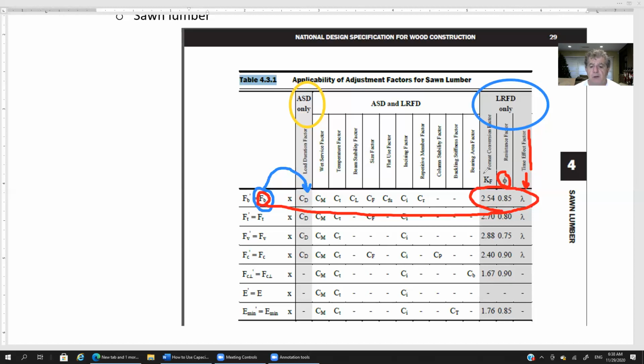A lot of peripheral concepts that are touched in timber design, such as connectors, proprietary products, all of these other things, are pretty much exclusively dealt with in allowable stress values. So you will find yourself duplicating a lot of work. In essence, if you try to do it LRFD, you almost also have to do it allowable stress, because in many other instances, you're going to have to get allowable stress values.